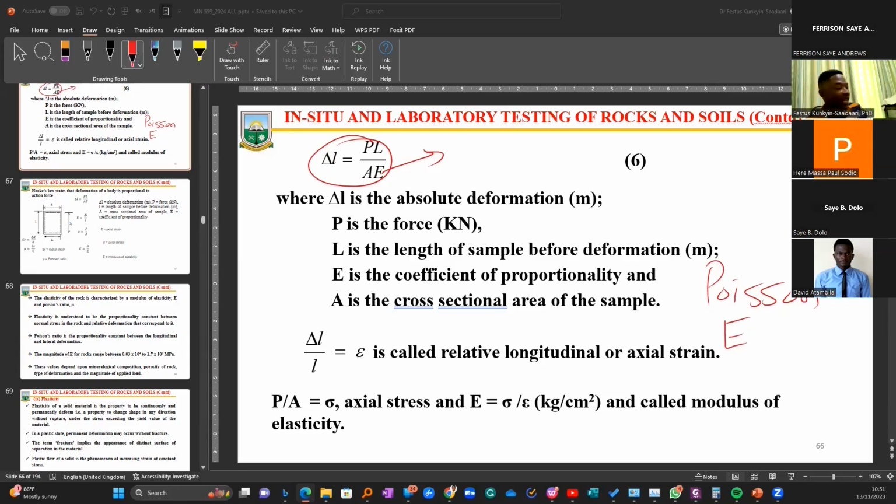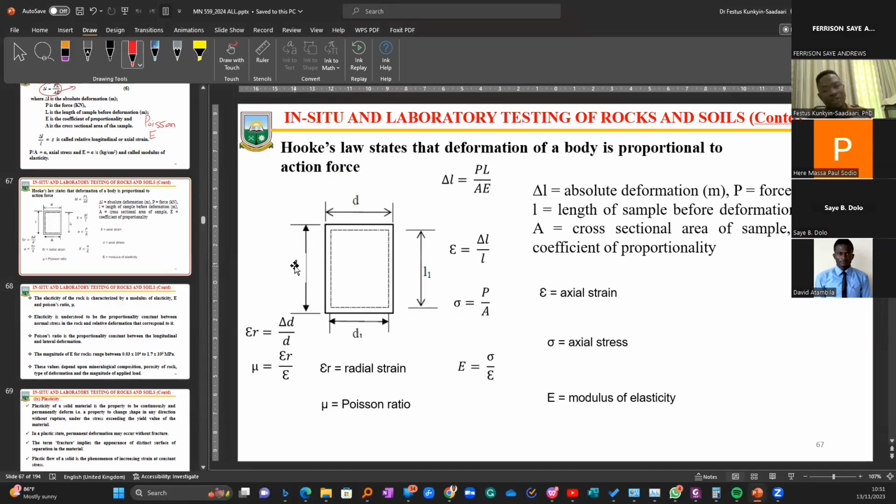And so again, with Poisson ratios, we are looking at higher values. But mostly, theoretically, we say the Poisson ratio of the rock varies from 0.1 to about 0.5. And it is unitless because you are using the longitudinal, okay? You are trying to use that of the lateral against the radial. And so it's a ratio of the squeezing when you compress the sample axially and that of radially. And so that ratio becomes unitless.